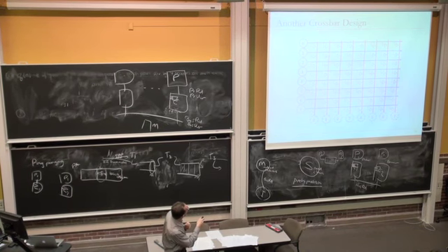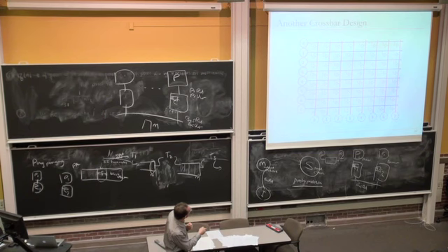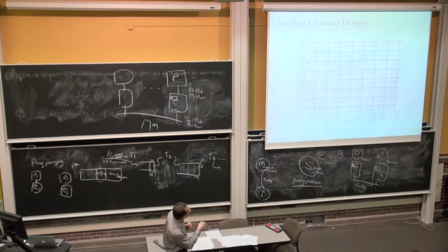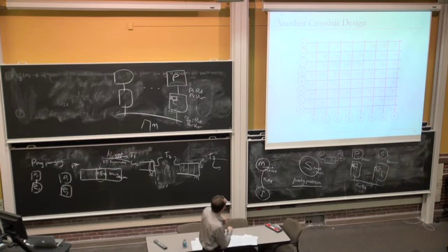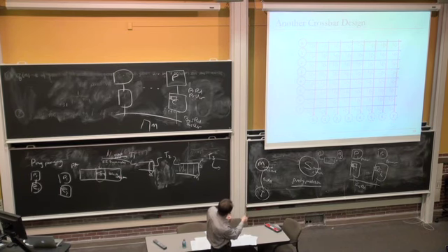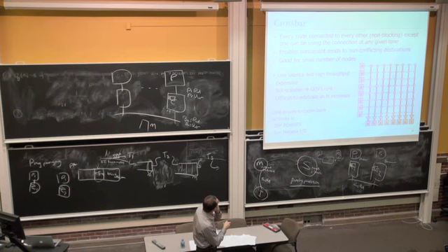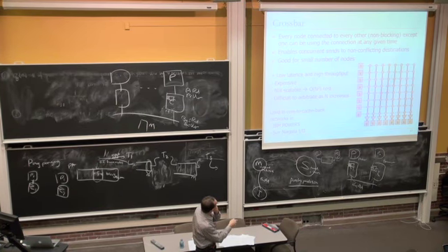So when node 0 wants to send a message to this node, this switch is enabled, right? When node 5 wants to send a message to this 4, then this switch is enabled, right? So you have O(n²) switches. And when nodes 0 and 1 together want to send a message to, let's say, 2, then there needs to be some logic that enables only one of these two switches, right? Okay, so I didn't show the control logic, obviously, here.